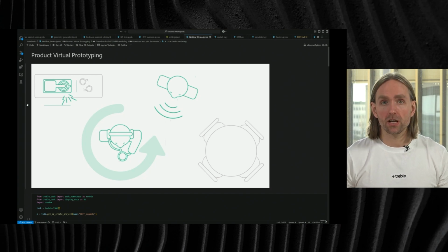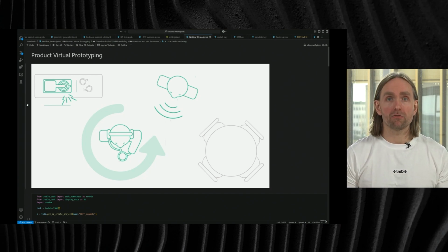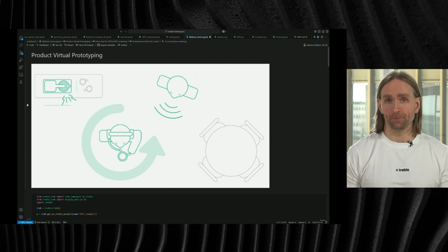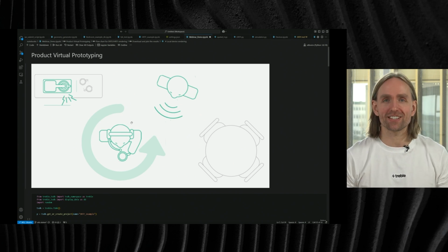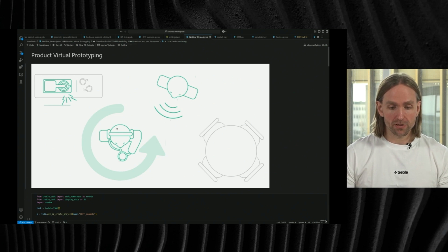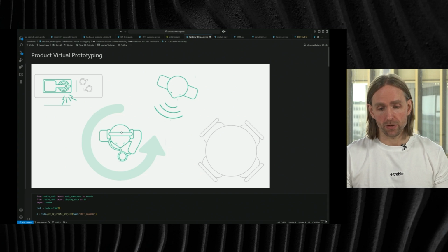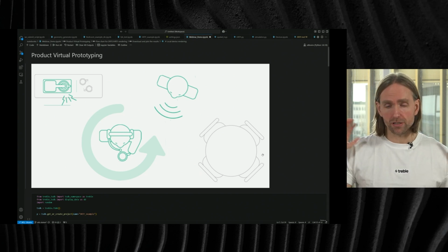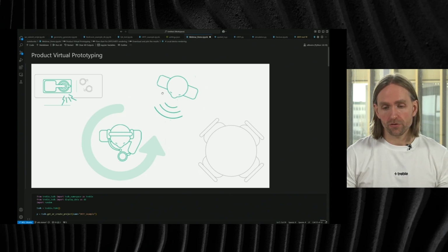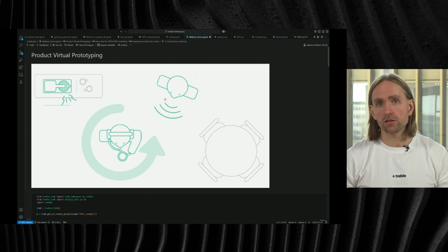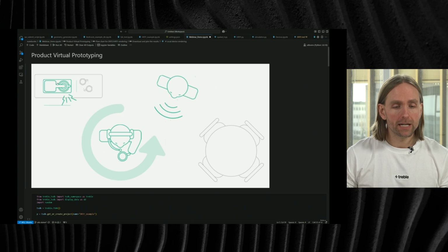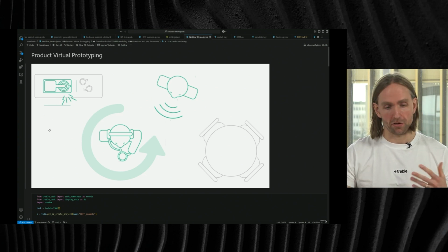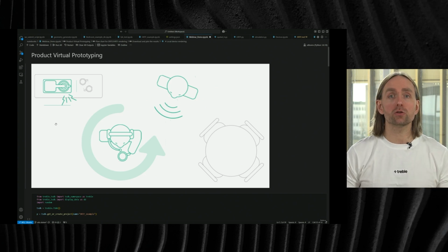So in this kind of scenario, you would like to set up a virtual audio scene. An audio scene can look something like this. It's a simplified sketch where we have the receiver device in question with some microphones on it. Then we have some environment with some furniture around. We have some, let's call them, target sources or speech sources that you want the device to pick up. And you have some distractor sources, like the coffee machine or whatever, that you want to reduce.